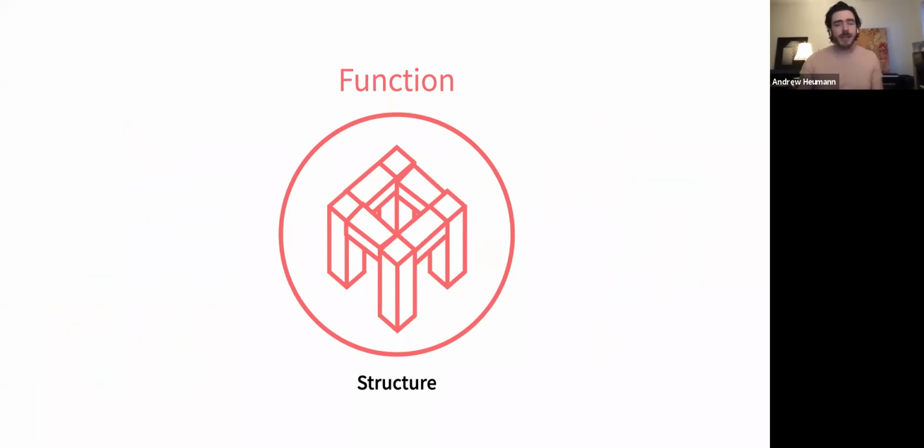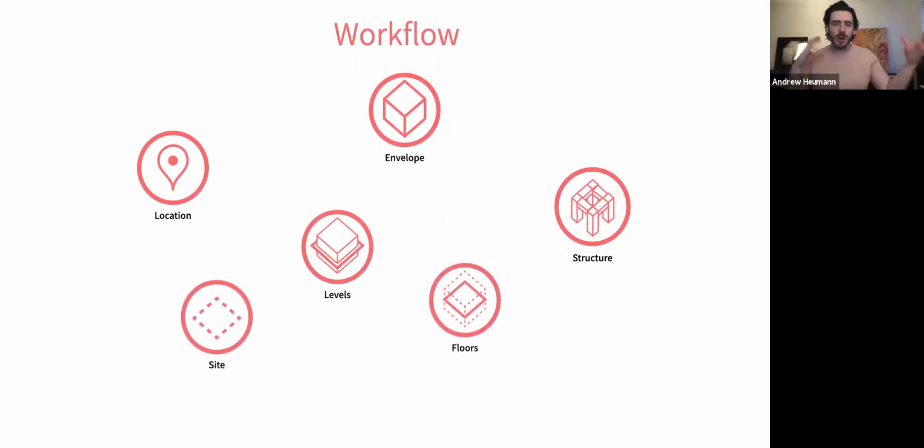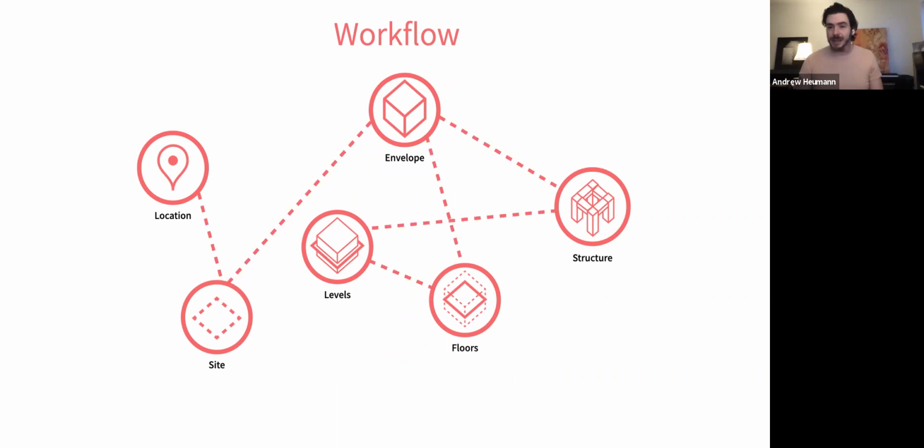And the thing that's powerful about this is that because we're explicit in defining these are the things that I need as a function, and these are the things that I produce, we can pull all of these functions together into a Hypar workflow and have them connect automatically. So I don't have to drag a wire to pull the levels from this part over to here. This function needs the levels, so it goes and gets the levels automatically.